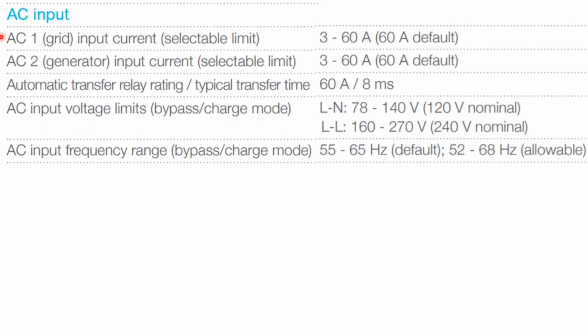It's just that tech support is not going to provide you with the design assistance to set up a microgrid. They're going to force that onus onto your electrical engineer. So essentially you can combine battery banks of multiple chemistries, but you're on your own for that. And what you'd have to do is monitor your grid just like the power company currently does to make sure that your grid levels are not getting out of whack.